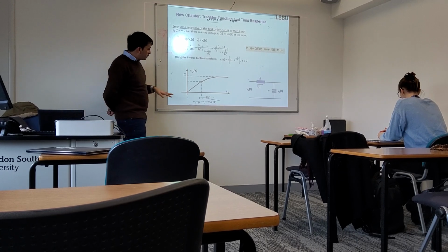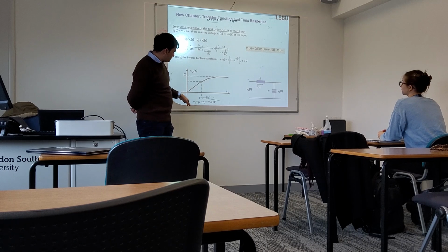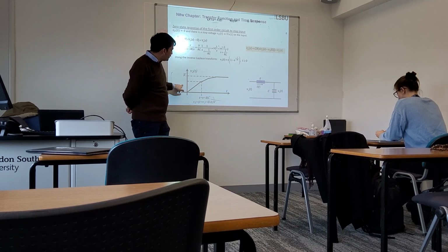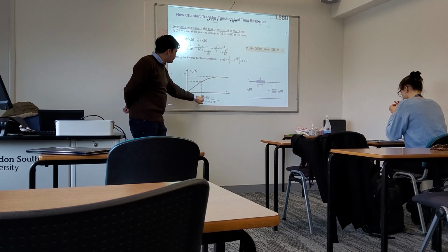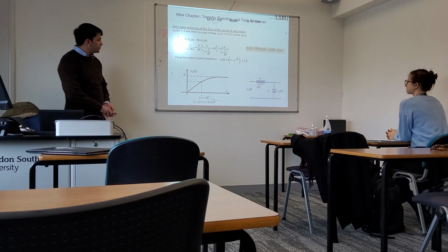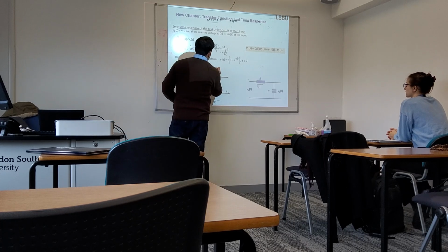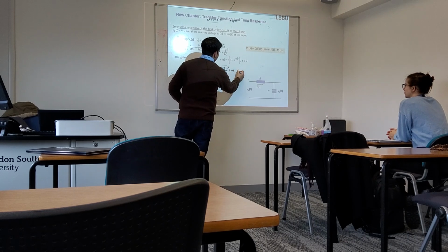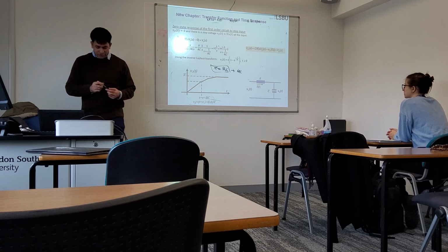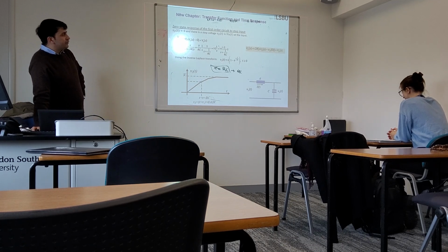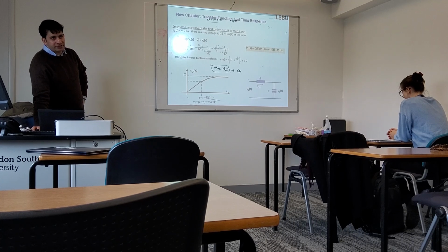And there is another thing that we sometimes say: when your value reaches 63%, this time is called tau. This time is basically called the time constant, and we represent it as tau equals RC. This is the time at which we reach 63% of the final value. This time is called tau. Okay, so this was the zero state response to a step input.